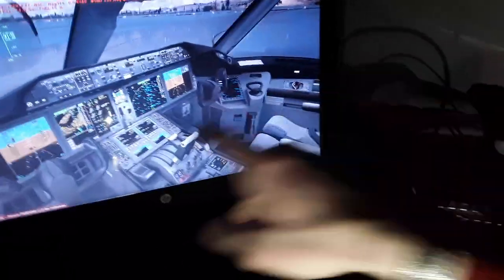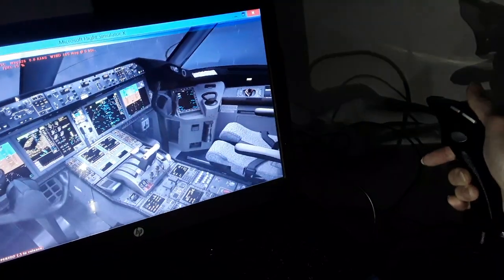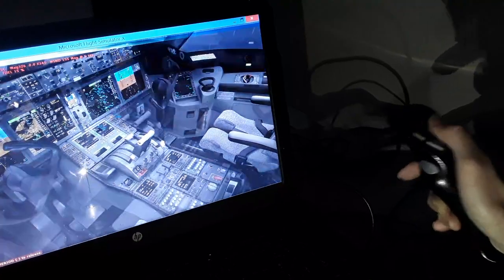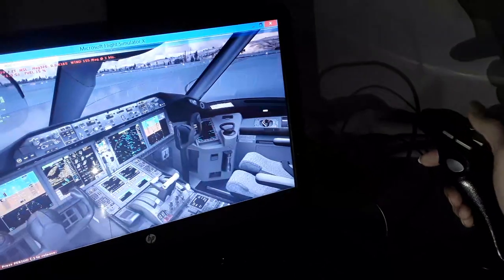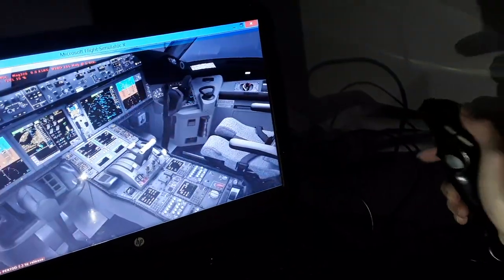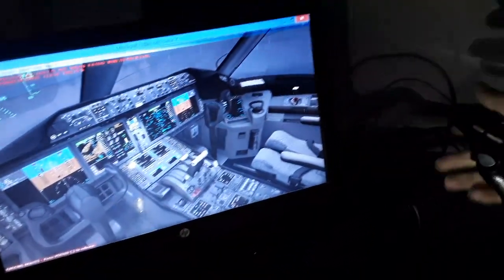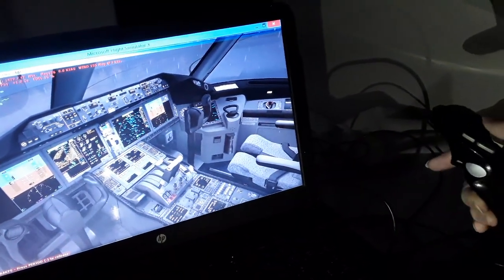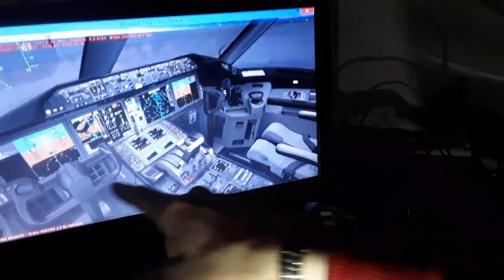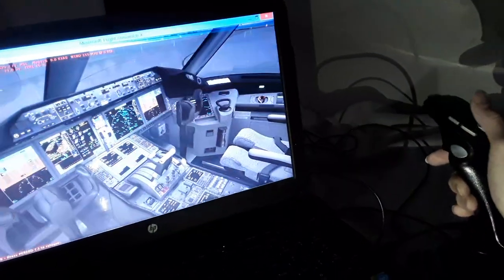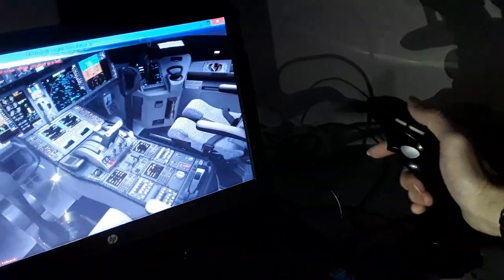Also in the Boeing, both sides are interconnected and move together, as you can see, the yoke and the control wheel. So you need to override either side. If you have a failure, for instance, you need to apply some force from either side in the Boeing aircraft. Also the rudder pedals, both Airbus and Boeing, are interconnected and move together in all functions. And also the Embraer and CRJ aircraft are quite similar with the Boeing yokes and horizontal trim stabilizer and rudder pedals.